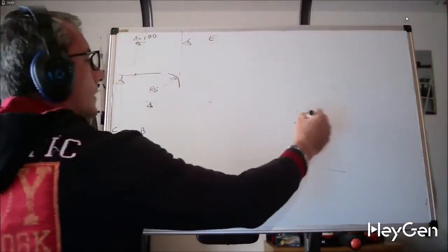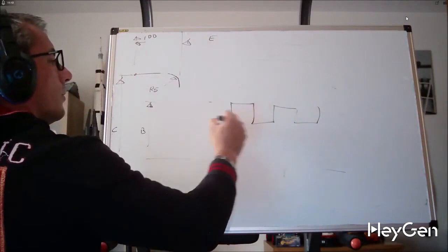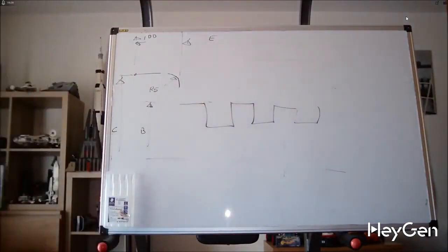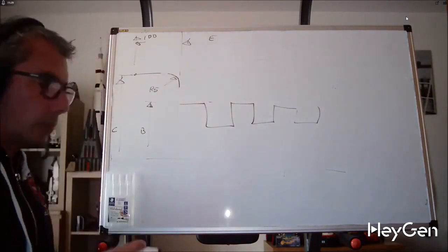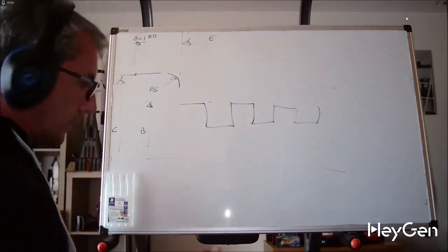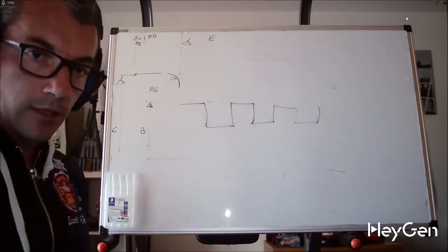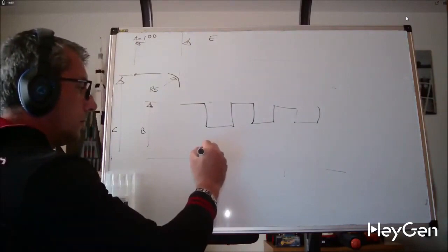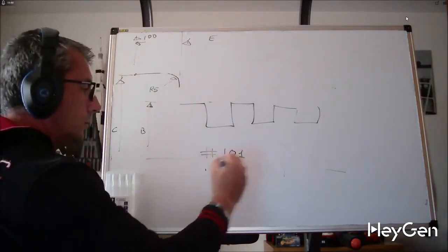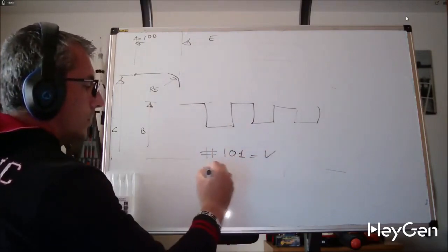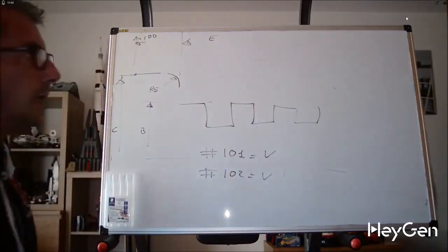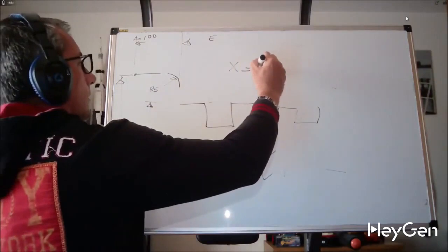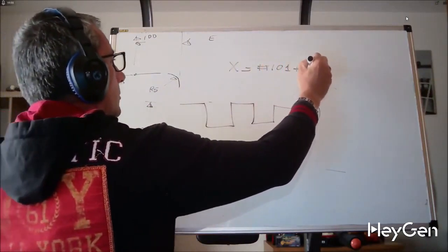For making the grooves, let's take the piece we used. We'll slightly modify the little program we used for the sub-programs, and you'll see how simple it is. So let's remember that in the simulator and on iFanuc, the variables are not A, B, and C like on many CNCs, but are percentage 101 equals value, percentage 102 equals value. FANUC does not allow the possibility of writing X equals percentage 101 plus percentage 102.